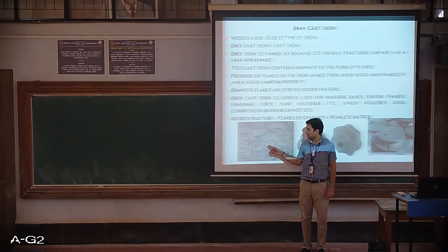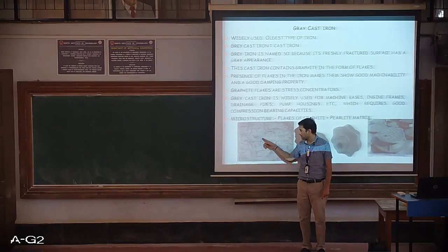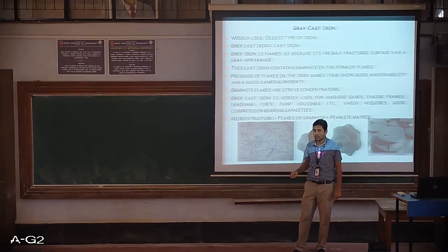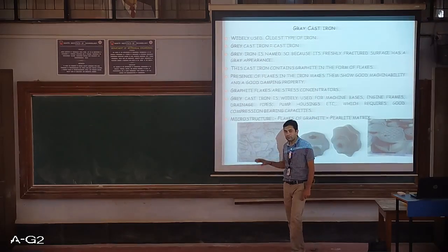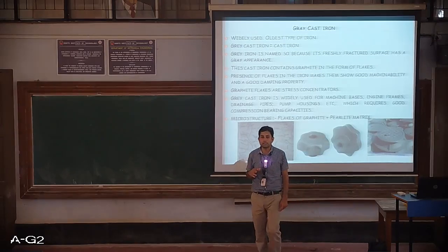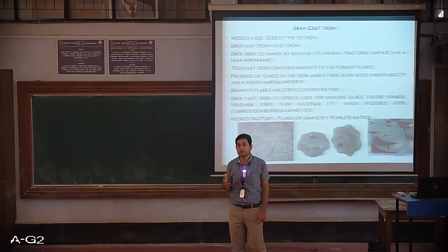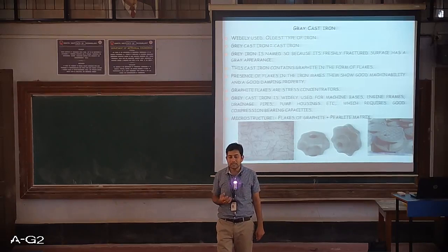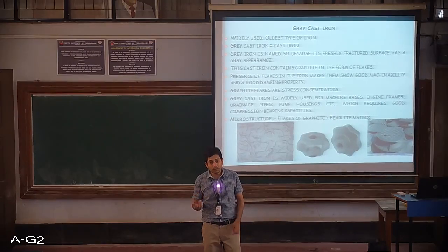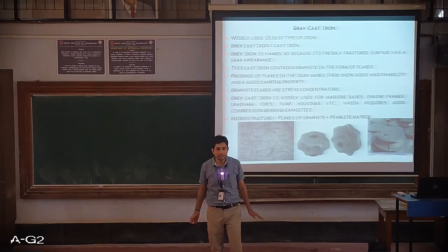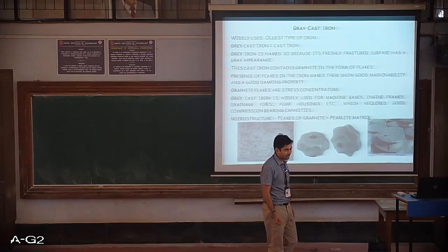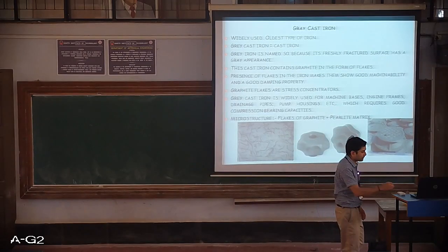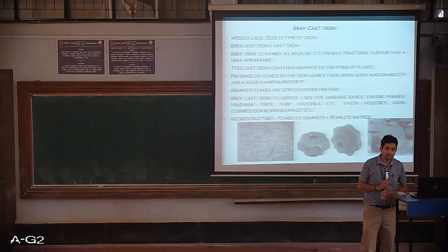This property of the metal showing graphite flakes does affect the final property. Because of the presence of these hairy flakes, the damping property and even the machinability of the metal become better. So this is an advantageous fact. However, if more of this is present, it is also a decreasing aspect for the mechanical property of the metal. So it should be present in a very optimum manner.